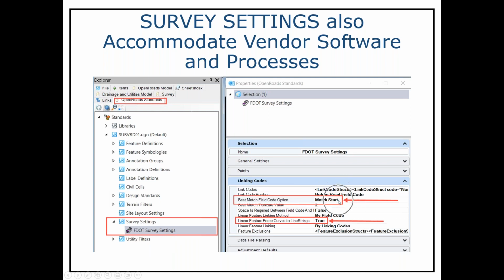Now, this used to be true/false in 10.10 and below. It was a true/false statement. So the problem is if you have a 10.10 or below survey and you bring it forward into 10.12 or 10.11, it's going to have a problem reading your features because they didn't have a direct conversion from true/false to the possibilities.